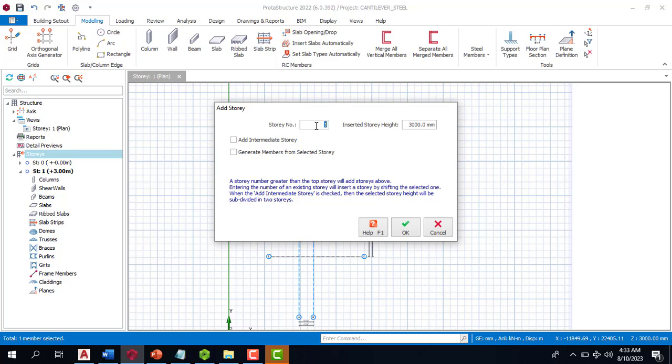Then the steel column, the entire overall height of that column, is going to be another story on its own. So that's 2 stories already. For now we are going to type in 2 as the number of stories. If there is need for us to create another story, we are definitely going to do that as we proceed in the modeling.